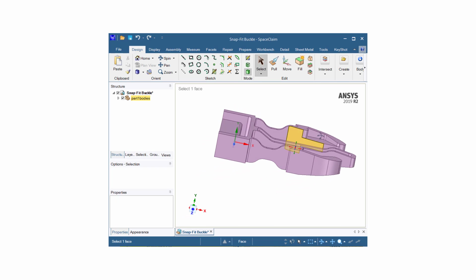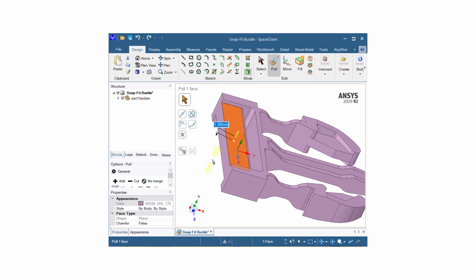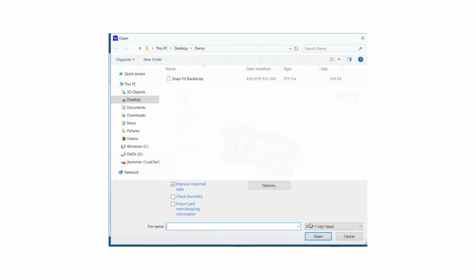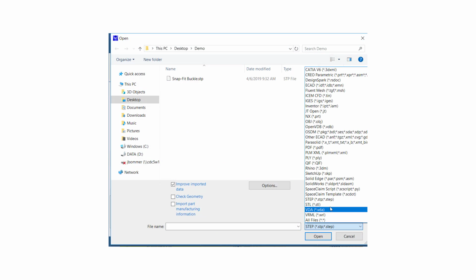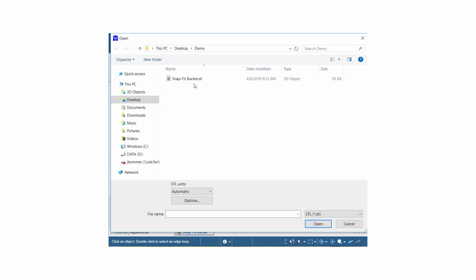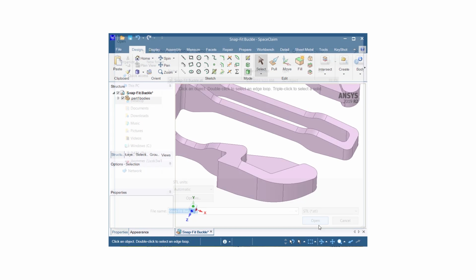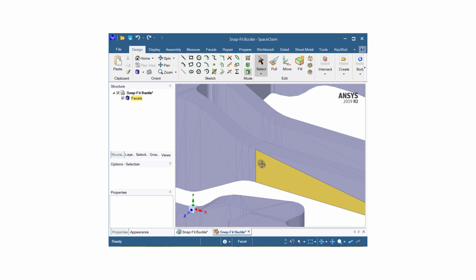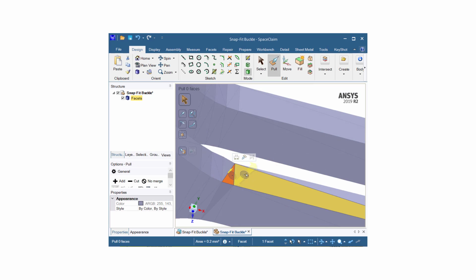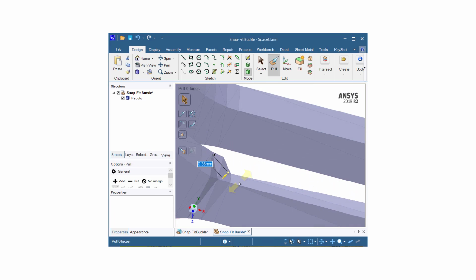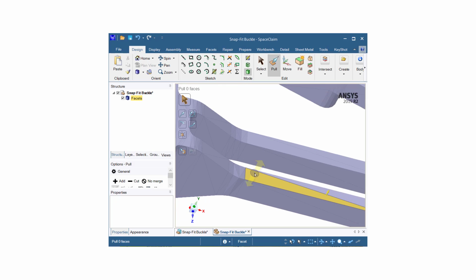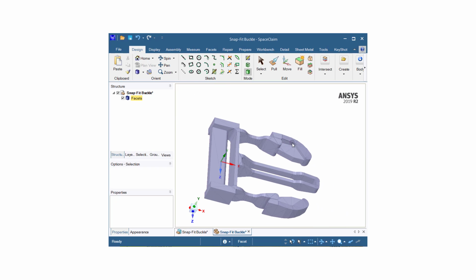We can see that editing the CAD model is very easy when operating from a NURBS geometry, and we have a wide range of flexibility. Opening the exact same model as an STL format, however, shows a very different behavior. While it is certainly possible to manipulate the CAD, the connected polygons that form the tessellation or the mesh make it much more difficult and cumbersome to edit.